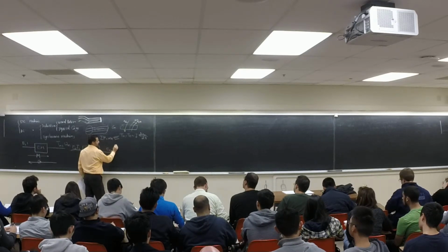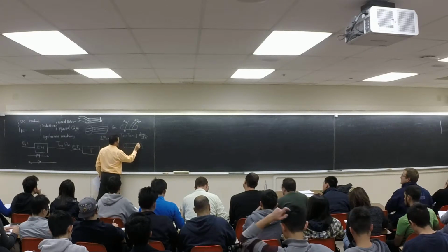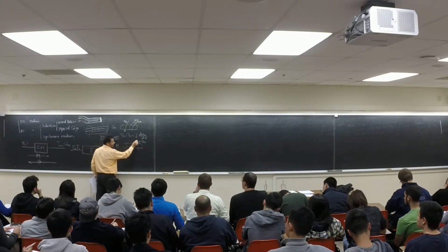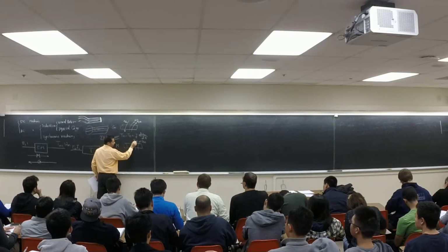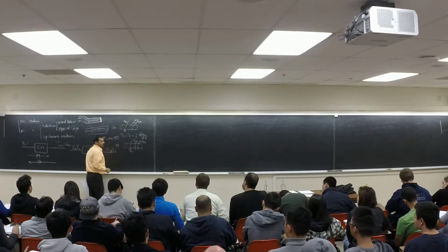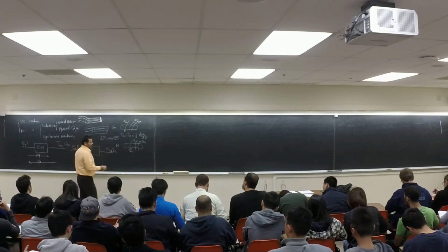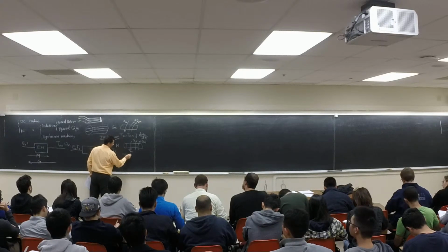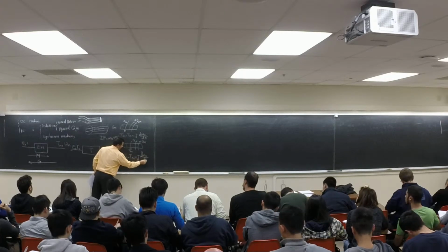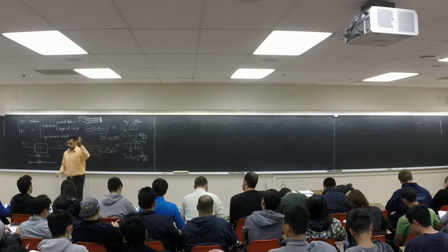If it's a motor, again, if the machine is rotating in this direction, electrical torque is going to rotate the machine, and the mechanical torque is against the rotation of the machine. So if you want to write a differential equation for this one, you say Te minus Tm equals J, and J is the moment of inertia of the rotor.